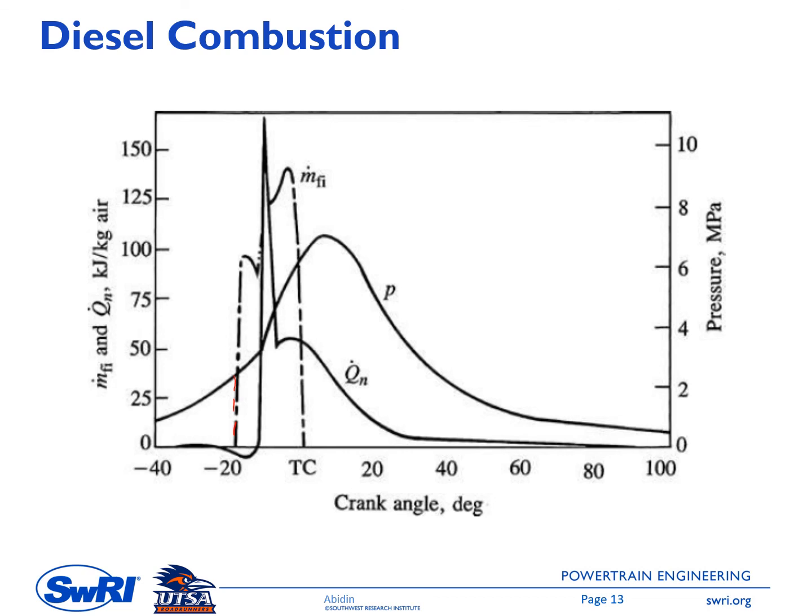And then, as I mentioned at the beginning of this presentation, the combustion will start after a certain delay from the start of the injection, and this is the delay, you see. The solid black line here is the heat release rate.